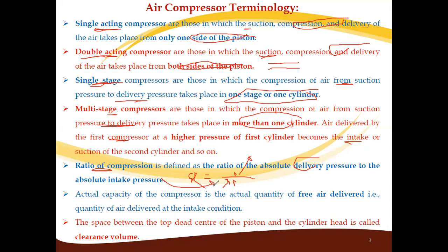Next important terminology is known as FAD, that is free air delivery or free air delivered. So the actual capacity of a compressor is the actual quantity of free air delivered. That is the quantity of air delivered at intake condition, that is called free air delivery.